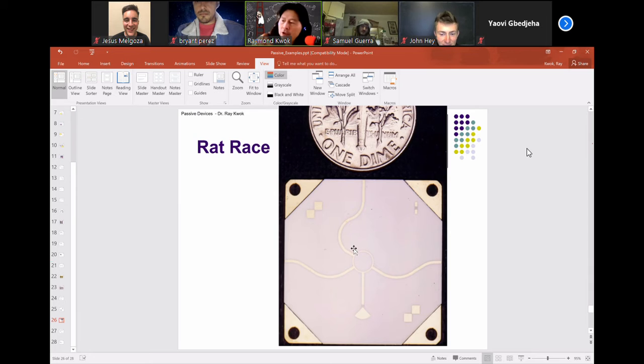Do you know why people use gold? Gold is not the best conductor, right? I mean, copper and silver are better conductors. Why do we use gold? It's corrosion resistant. Silver would get oxide too easily, tarnish. No tin whiskers. Yeah, and that too. Oh, you heard about that?